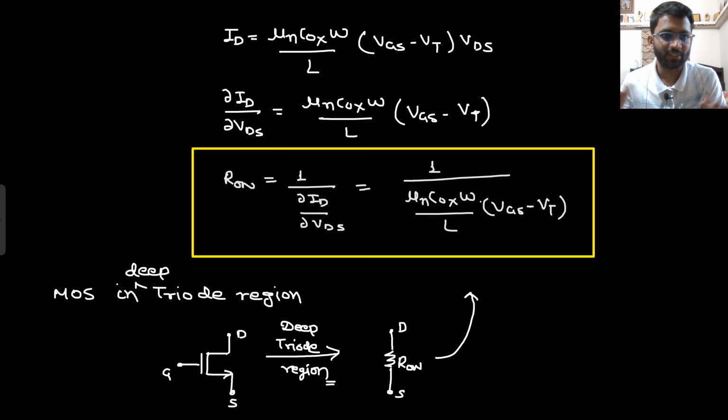By using all these things, whatever we have studied in MOSFET till now, we have seen the MOS physics, then we saw some questions, now we have seen the important parameters. First we understood why we need to bias, so that the transistor turns on, then we can amplify. When we saw the biasing, we saw that del ID by del VGS is a very important parameter. Higher the slope, more the gain.